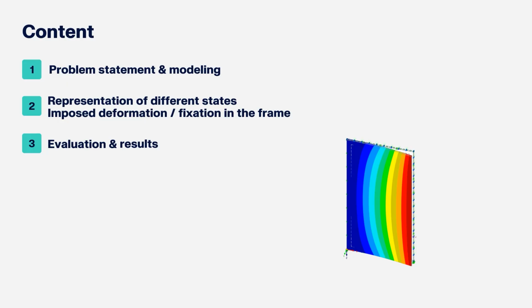Why are we doing this cold formed process? I can imagine two cases. In the first case, it's a planned state that we have a non-planar facade with a small radius, and it is easier to create the glasses in the plane state. And for the installation process, it will be bent.